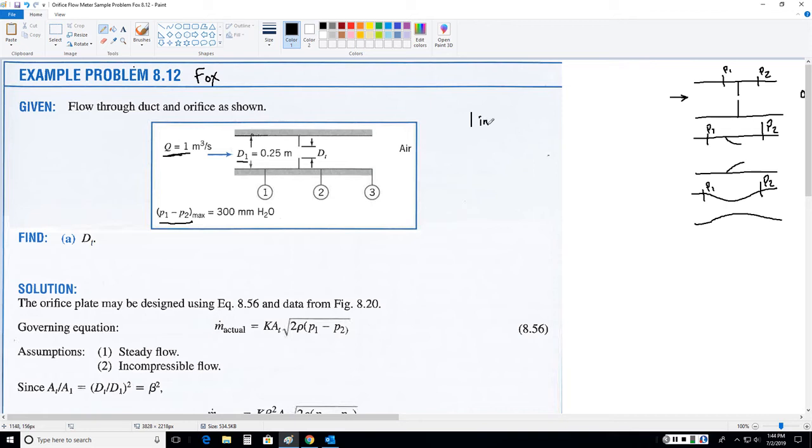You guys have a 1-inch pipe. In reality, yours is 0.987 inches. That's the ID. So your D1, your diameter, is known. You also have Q, which you have in cubic inches per second, and you also have delta P. Obviously, you have it in inches of H2O, which you need to convert to pascals or PSF in order to make sense of some things. I'm going to put in red, you have this, and you have that. This is your delta P. And what you're going to be looking for is dt, which is the diameter of the opening of that plate.